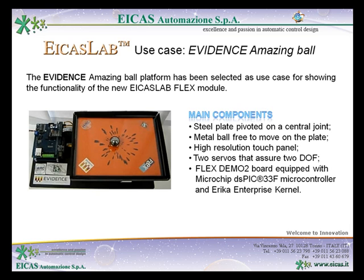The Amazing Ball platform consists of a steel plate pivoted on a central joint, on top of which is placed a metal ball free to move. The system has 2 degrees of freedom, ensured by 2 servo drives connected directly to the plate that allow it to tilt. The coordinates of the ball are measured with a high-resolution touch panel mounted on the plate surface, while a Flex Demo 2 board equipped with Microchip's dsPIC33F microcontroller and ERIKA Enterprise kernel commands all the peripherals.